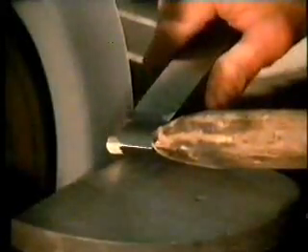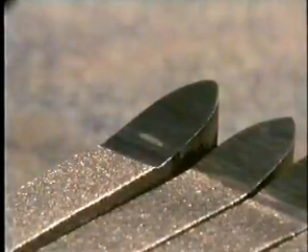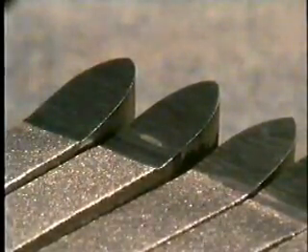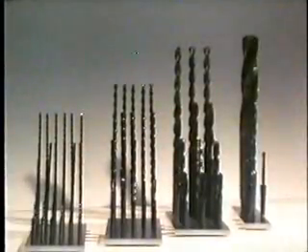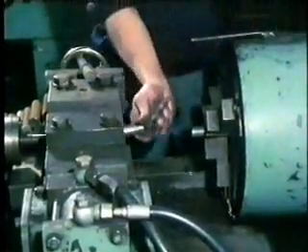The cutting edge can be reground again and again until the high-speed steel is completely worn away and the toughened shank is reached. At this point, the tool is scrapped. The same principles are used in other cutting tools, such as high-speed twist drills. As in the lathe tool, only the cutting end is made of high-speed steel. In this particular example, the cutting end is friction welded onto the toughened shank.